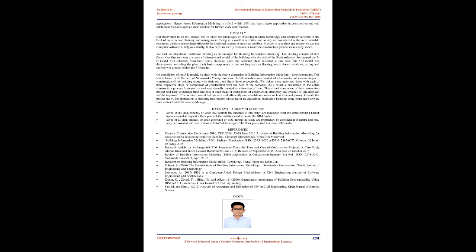On completion of the 3D model, we dealt with the 4th dimension in building information modeling, time constraints. This was achieved with the help of Navisworks Manage software. A task schedule was created which consisted of various stages of construction of the building along with their start and finish dates respectively. We linked these tasks and dates with each of their respective stage or component of construction with the help of the software.